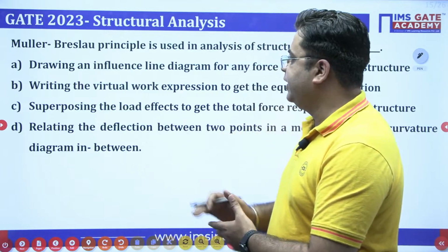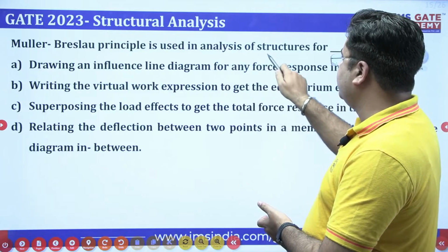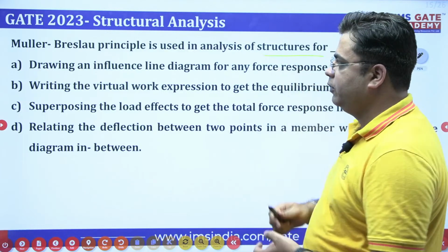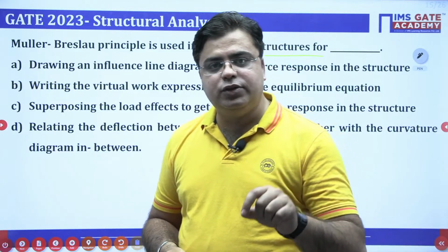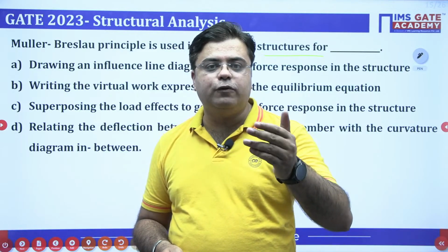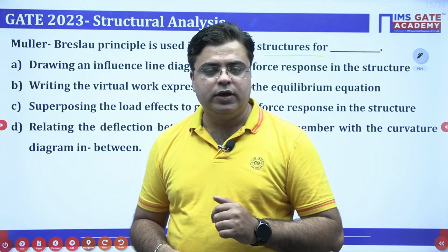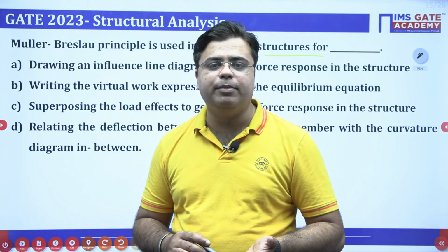This is GATE 23. The question says that the Muller-Breslau principle is used to analyze the structure for. So my dear students, first of all, the Muller-Breslau principle is used to draw the influence line diagram with respect to various force responses. The forces can be support reactions, shear force, or bending moment.